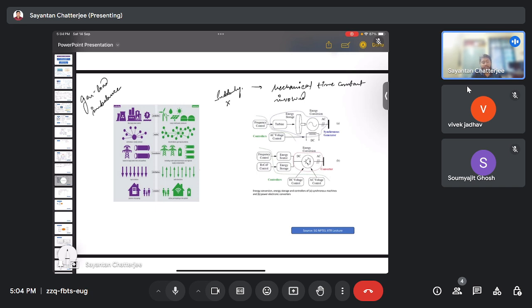This is the case where the conventional system works. Since the rotor is rotating with a kinetic energy, with this sudden deviation or sudden dip or rise, the rotor's kinetic energy is delivered as electrical energy outside.